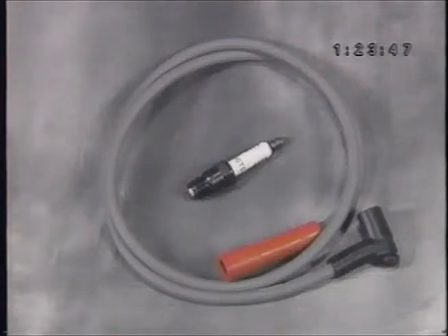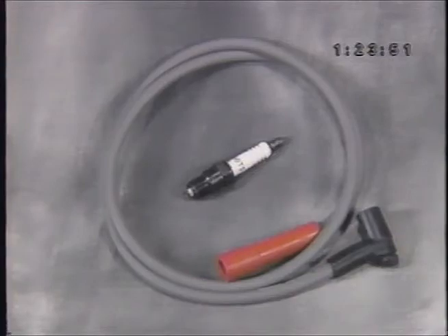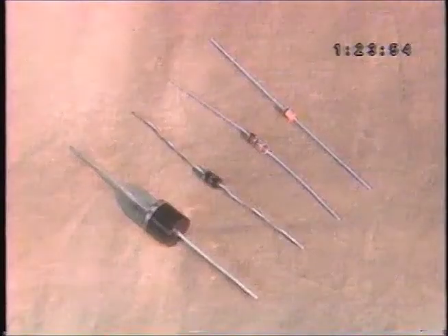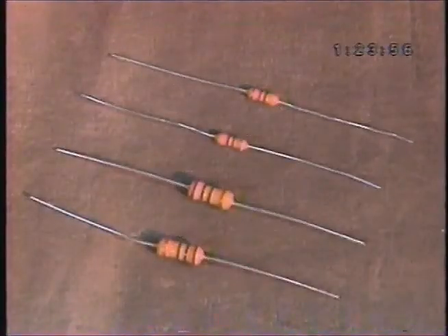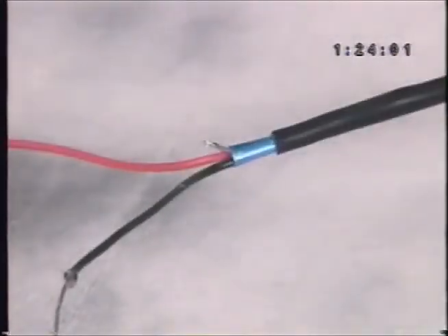Automobile manufacturers go to great lengths to reduce or eliminate electrical noise. Resistor plugs and resistance ignition wires are two common methods for reducing electrical noise from the ignition system. Diodes, resistors, capacitors, and shielded cables are all devices used for controlling electrical noise. In this lesson, you'll use Scopemeter to identify a couple of common sources of electrical noise: air conditioning compressor clutches and blower motors, and compare noisy signals with properly damped waveforms.